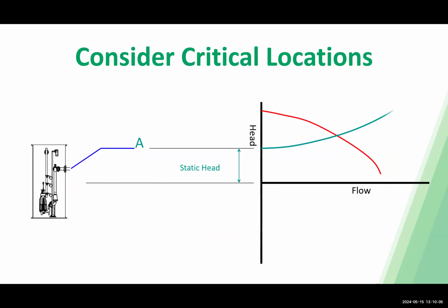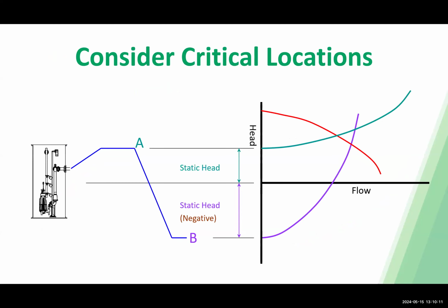You can also have instances where your static head at the high point is actually above the shutoff head of that pump, but you'd only be considering that low point in the system, where you'd be like, yeah, any pump is going to work here. But that pump wouldn't be able to overcome the initial pressures of that system after the first time it is run.